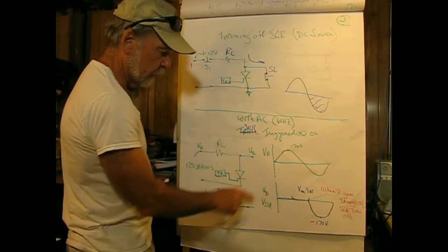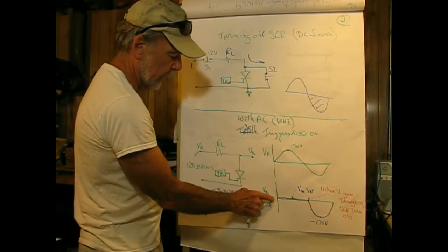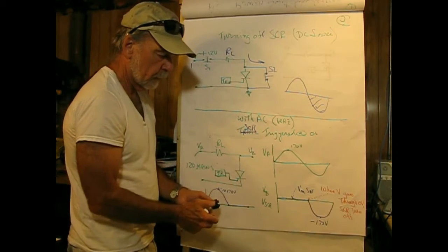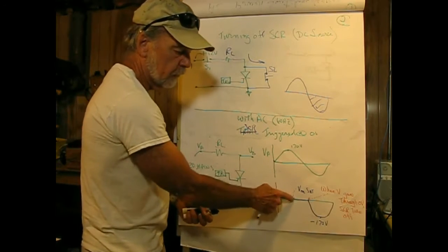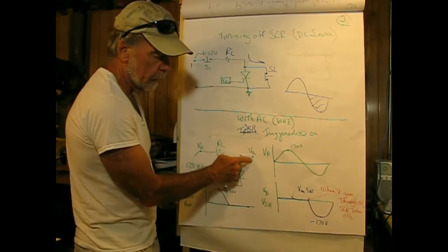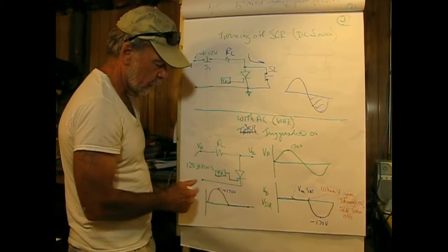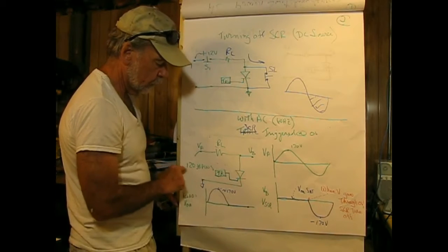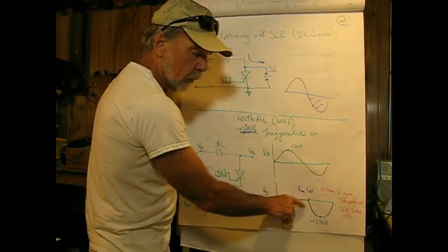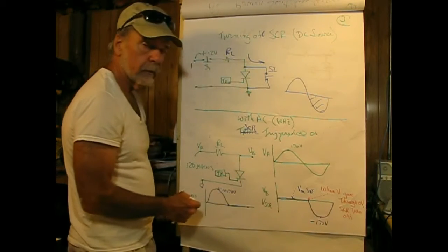So what that means is that if we're starting out a sine wave, we're right here, and if we're going to trigger this and turn it on, so it's going to be turned on, and right now we're going to say that the voltage drop across it is very low. I call it V on saturation. What we would see if we took a look at the point B here would be 0 volts, because this is on and connected to ground, or the return on the 120 mains. Now on the second half cycle where it is off, all of the voltage would appear across the SCR.